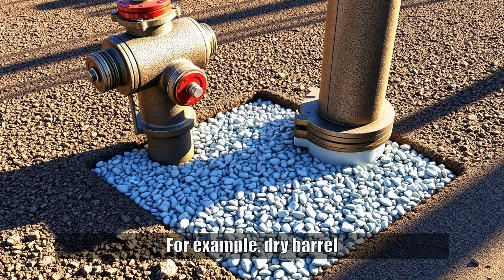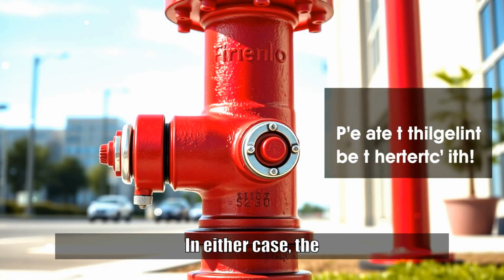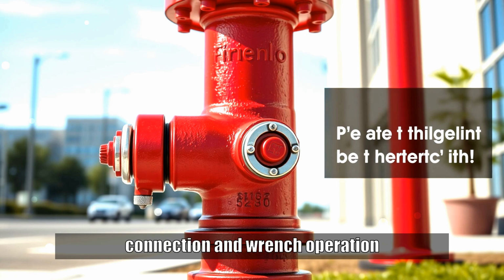For example, dry barrel hydrants need a proper drainage field of gravel below the barrel to allow water to drain and avoid freezing damage. In either case, the hydrant must be set at the correct height, with the outlets 18 inches (45 centimeters) above ground, ensuring easy hose connection and wrench operation.